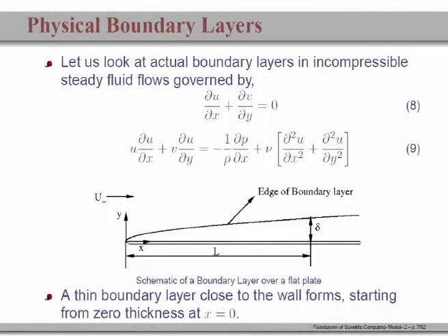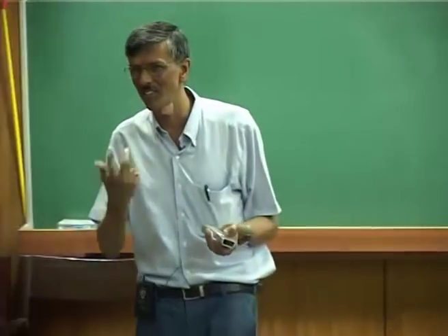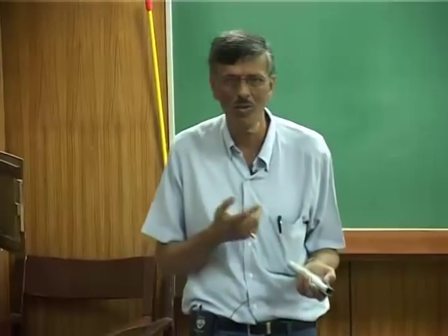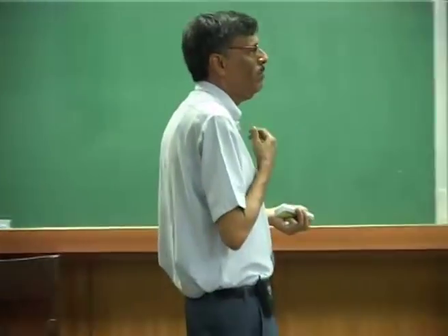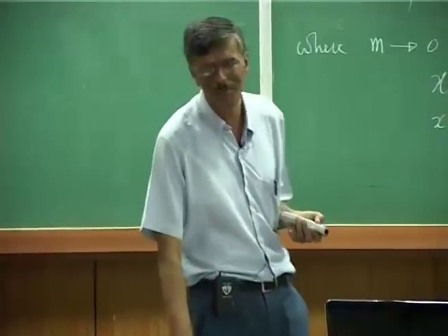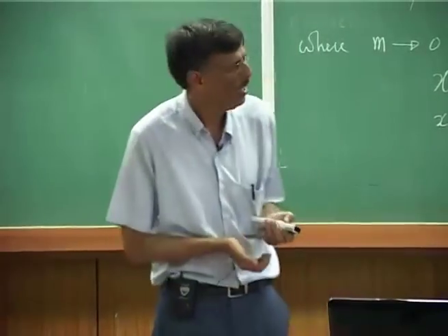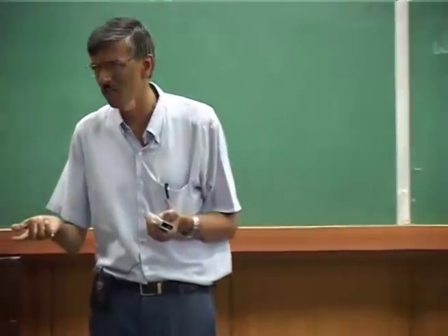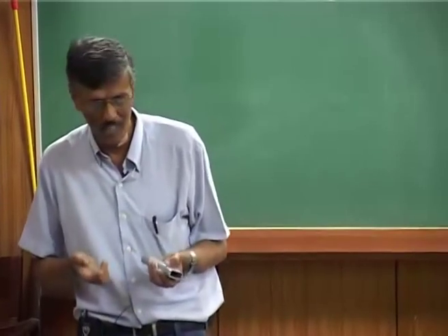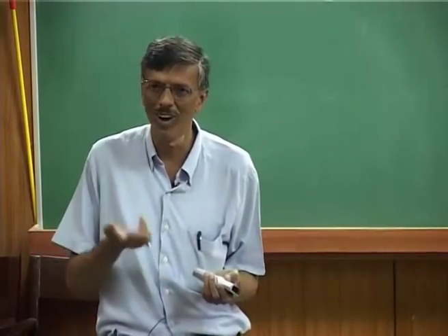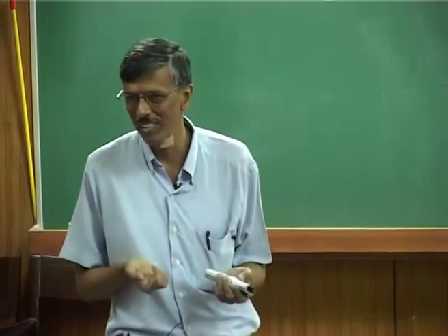The nonlinearity that is here in the momentum equation does not allow us to have a closed form solution. So, that is why these days many of us try to solve the problem using computers. When we solve the Navier-Stokes equation without using any additional assumptions or approximations, we call them direct numerical simulations.